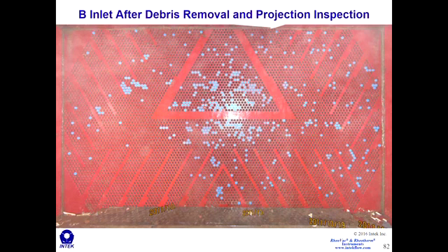Okay, and so this is an image to give you an idea of what we expected to happen. This is a photograph of the lower half of their tube sheet. After the test was done, I crawled into the water box and manually inserted these tubes for another reason. And I took several photographs of the tube sheet here and stitched those photos together and corrected for parallax. I created this image after the test was completed. This gives you an idea of what we hoped would happen, that these oversized balls would get lodged into the inlet tube sheet. So let me show you the data and show you what actually happened.